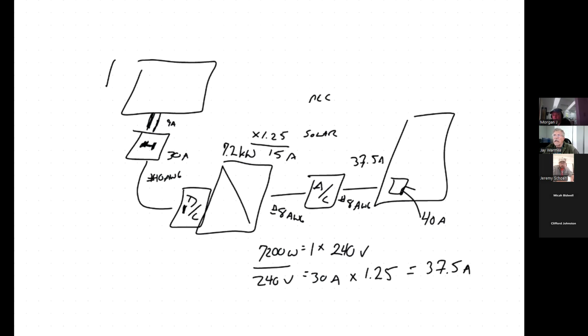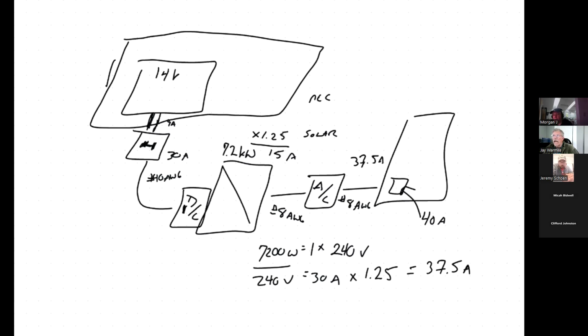So if you're only taking up maybe a third of the roof with your 14 kW array, and if you expanded it out to the whole size, then design your wire for that whole size. Even though you only need the 14 kW, so maybe we could get by with 10-gauge wire. But if you went and filled up that whole roof plane, maybe you'd need 6-gauge wire.